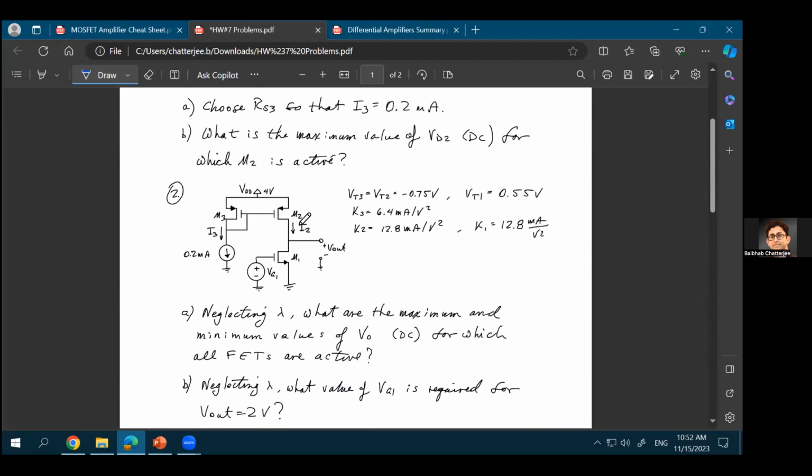And in this case, what you really had is this particular circuit. Now, what is this circuit? Your input is applied at the gate of this transistor, right? Your source is grounded, and you're taking your output at the drain. So that's basically a common source amplifier. Okay, so that's your common source amplifier. But what is the load to your common source amplifier? The load to your common source amplifier is the resistance that you see looking into the drain of this top transistor.